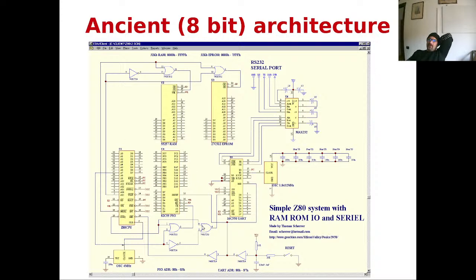8-bit microcomputer with a bunch of chips constructed around the Z80 CPU, where we can see that there is a memory chip. We can see that there is an EEPROM, which stores the non-volatile program. Basically, it can be the operating system in the old times of the CPU, so it's the program that the CPU reads when it's just started. We observe that the address bus over here is typically shared between all the same peripherals, which means that the bus line A0 goes to the bus line A0 of both the RAM and the EPROM. While the higher order of addresses are typically decoded by a certain logic that decides which of the two chips to enable based on how the memory is mapped.